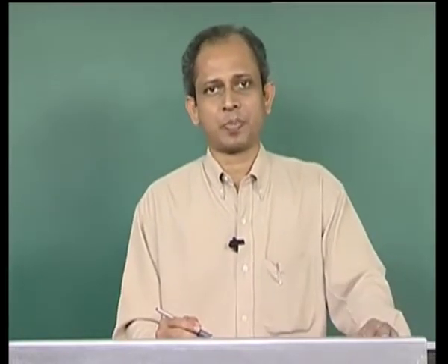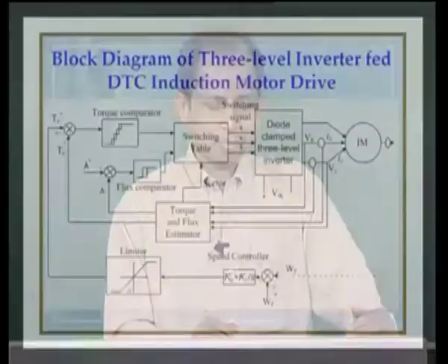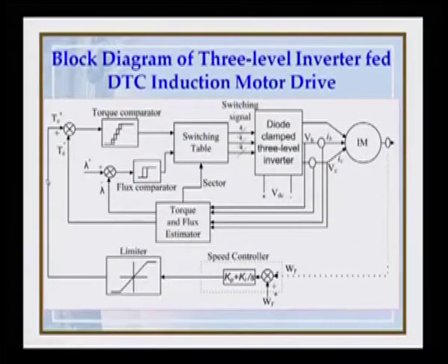Obviously, in a machine we will have a maximum possible torque, because torque and the currents are related. So, we limit the torque to a maximum limit and a minimum limit, and hence we need a limiter. And then this limiter will limit the value of the torque, and it gives basically the torque reference.